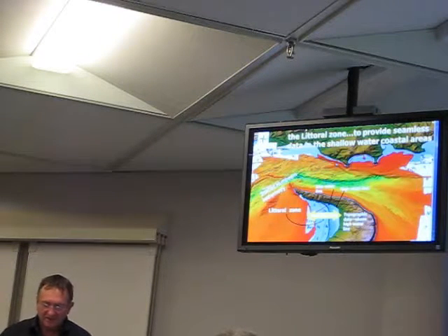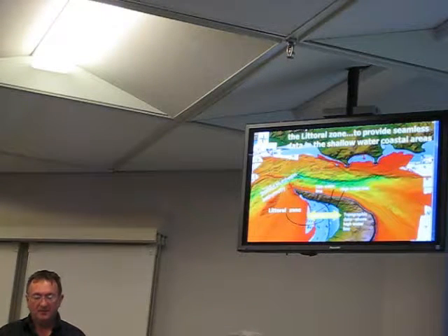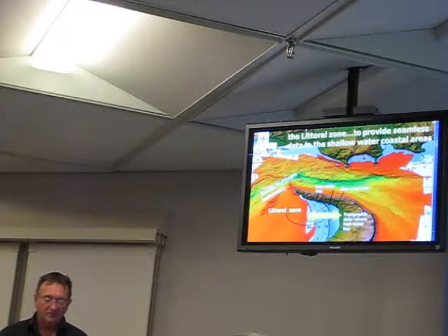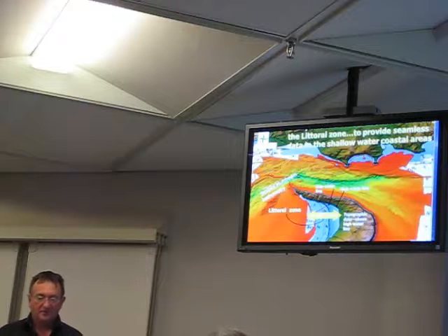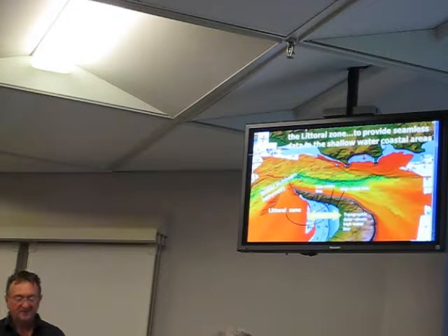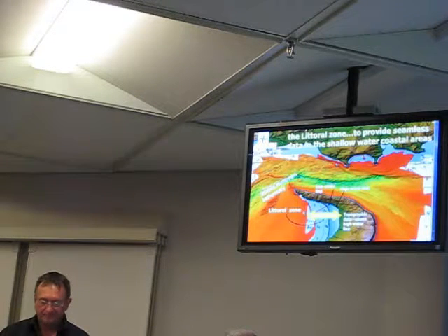So as I mentioned, CHS, our priority is for LiDAR. Our main application for LiDAR is the littoral zone from above the high water line, just into the topographic area, through the foreshore, and past the low water line, out to whatever depth we can get with the LiDAR system, and then to join up with existing data usually from acoustic multi-beam systems these days.